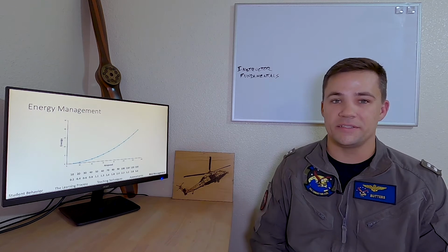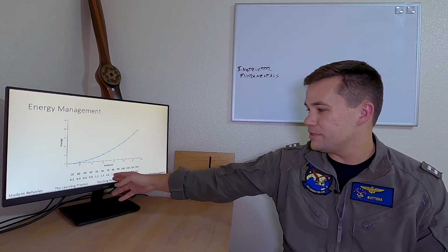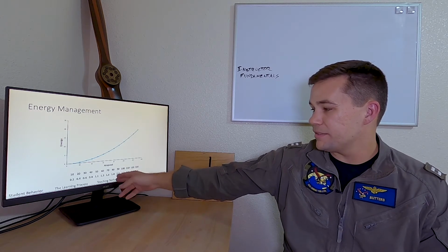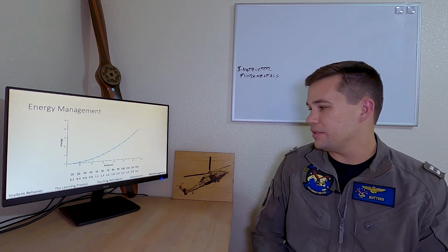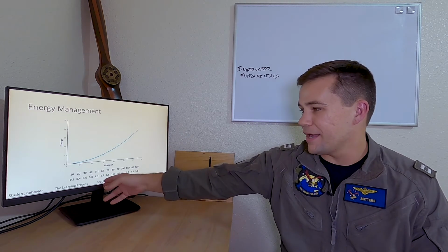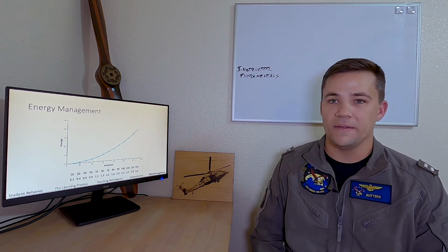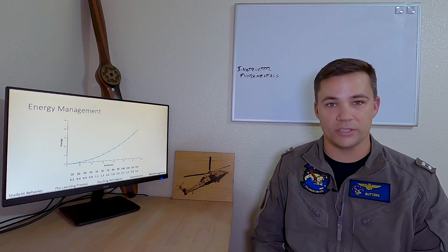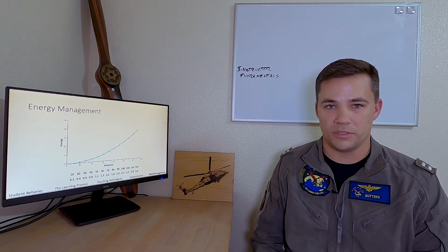Each of these is just for decelerating 10 knots. So if you decelerated from 100 down to 70, you'd have 2.3, 4.3, 6.1 units of energy essentially recapitalized from that airspeed. Whereas if you were doing that from 50 down to 20, you're looking at 1.9, 2.5, a significant difference. And as an instructor, you want to think about what role that plays in terms of your defensive posturing when you're at low altitudes, slow airspeeds, or you could potentially droop the rotor system.